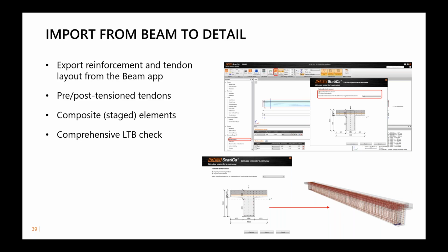So let's have a long span pre-stressed beam. Those elements are usually quite tall, and to reduce the weight of the member, you input openings. So from quite a standard example, you get quite a complex problem, because right now the beam is divided into B-regions and discontinuity regions.